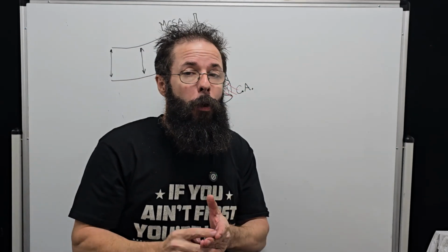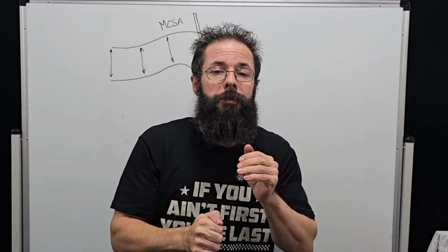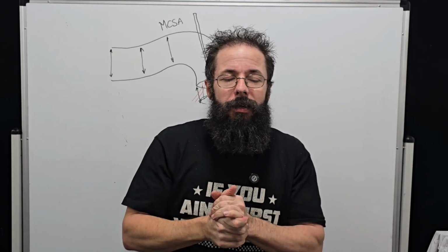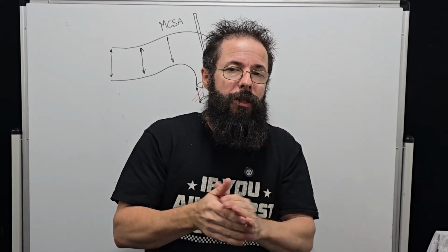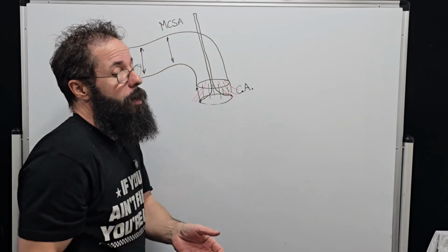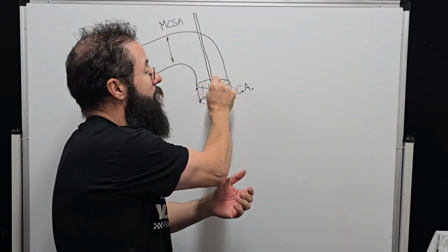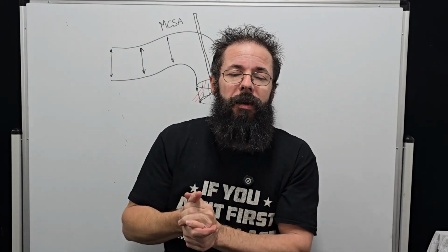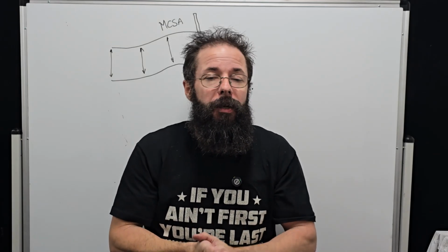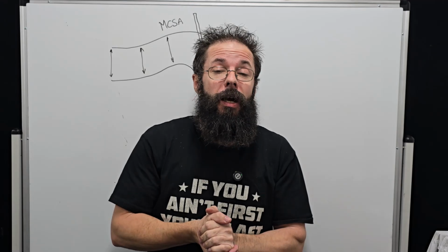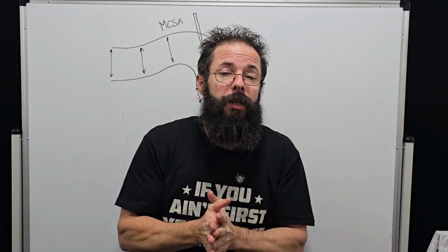And the saturation point is when that area becomes bigger than our minimal cross-sectional area in the port, meaning that until we exceed our saturation point, our high velocity area is always at the valve seat, meaning we can compensate for a poorly designed port if we stay under our saturation point, which in most cases, as soon as we start getting more serious, we can't.